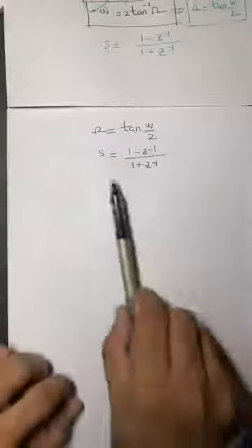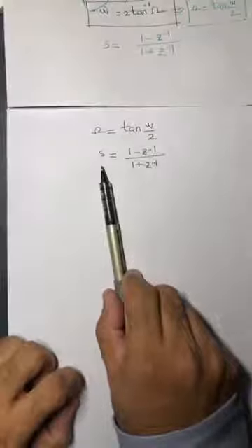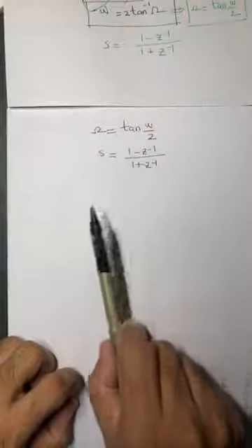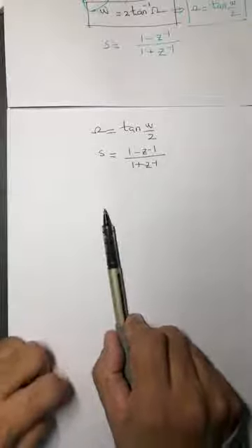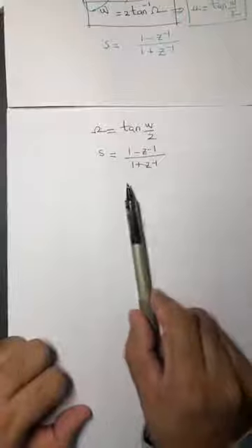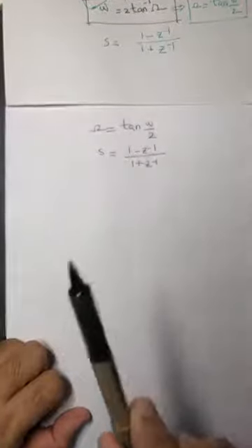Okay, you can just throw away all the electronics if you know the transfer function. Convert the transfer function into H of z. H of z gets converted into a difference equation. Implement the difference equation through a computer program. So almost any analog system can be converted into a computer program.